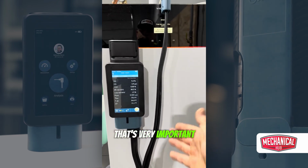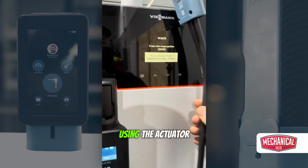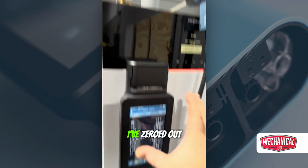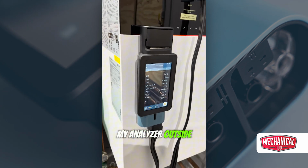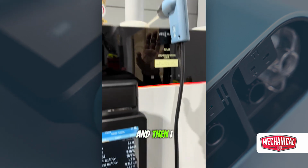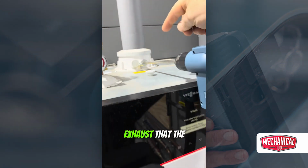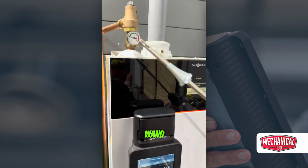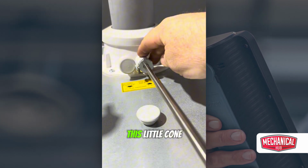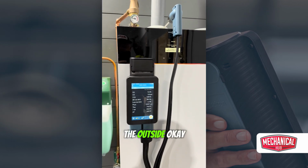And that's very important. So I've followed the instructions on the boiler. I've placed it into low fire mode using the actuator test functions of its control. I've zeroed out my analyzer outside of the space. I've pumped clean air into it, and then I insert it into the flue passageway right here, okay? So it's my exhaust at the end of that wand. It's going to be right about in the middle of the flue passageway. This little cone kind of allows it to sit in there tight against there. We're not pulling in air from the outside.